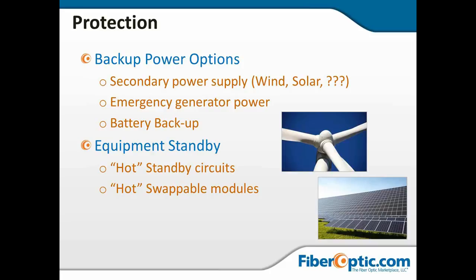I actually left that job shortly after that. They just didn't want to listen to any of my experiences, and they insisted on putting it on the ground. You want to be aware of the location of your emergency generators. If it's in a flood-prone area, make sure you've got it up on some kind of elevated platform so that you don't have saltwater inundation or flooding of your diesel engine.